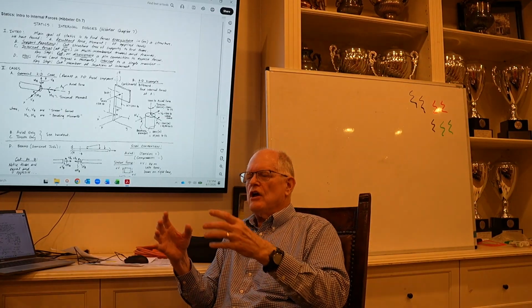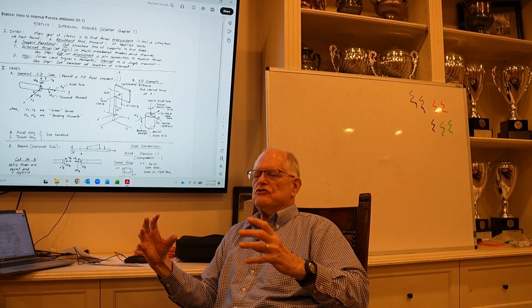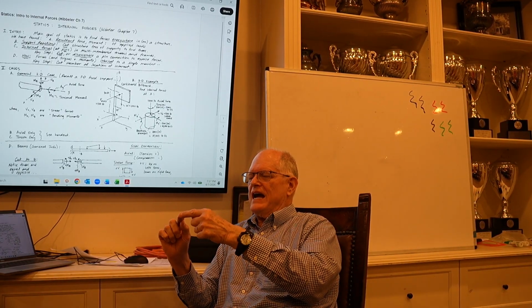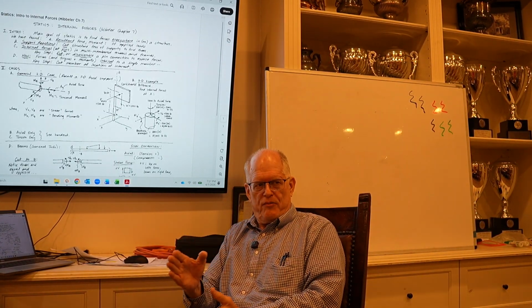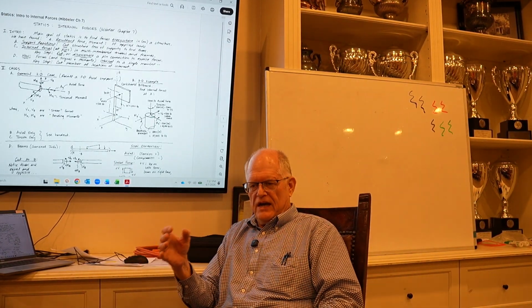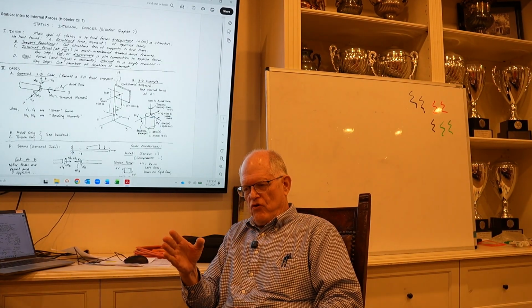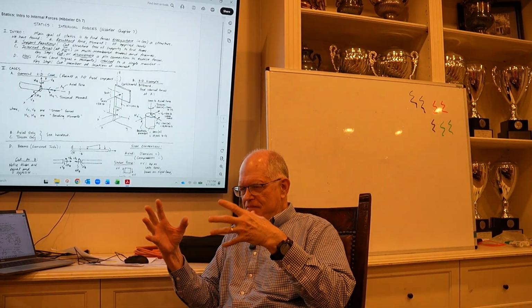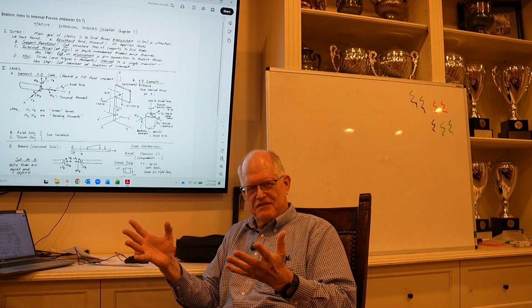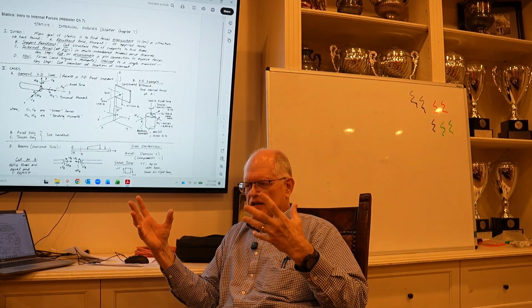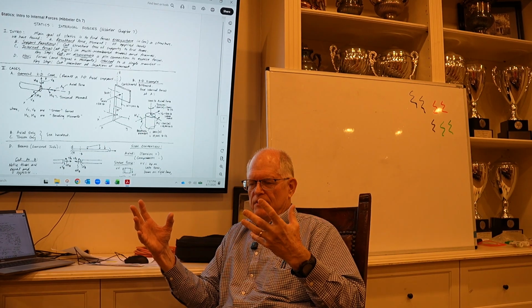But here now, what we're doing, instead of just looking at pin reactions that we've taken apart, now we're actually cutting members at an arbitrary place within a member. And there are actually internal forces. In any typical member that you cut, there's internal forces at that cut, okay? Because if you've got loading on a particular member,